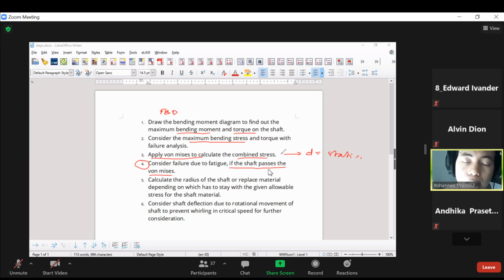So it makes sense, right? Because in fatigue, the strength of the material is reduced below the yield strength, I mean. So it means that we will use larger geometry, larger diameter, to resist the fluctuating load. Okay, so I hope that we can continue to discuss this until the time of quiz.